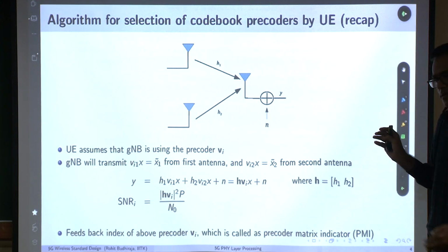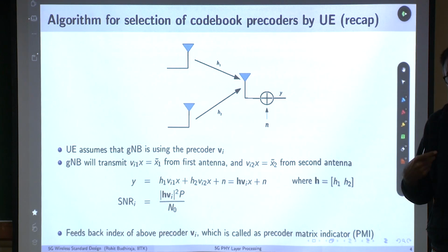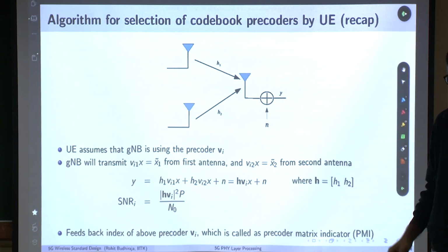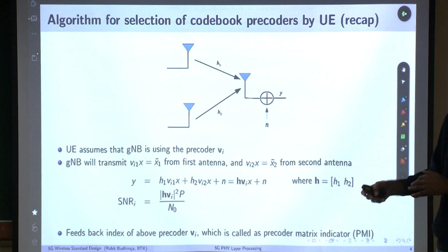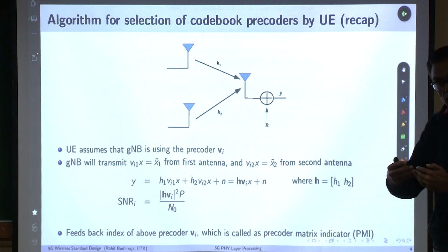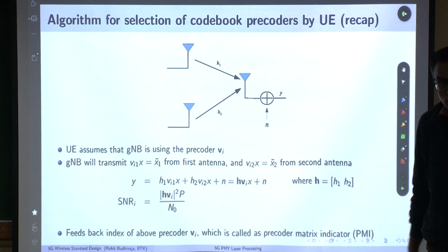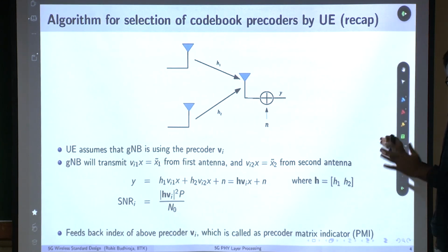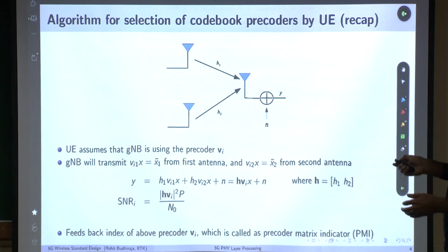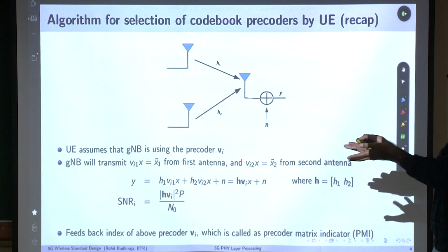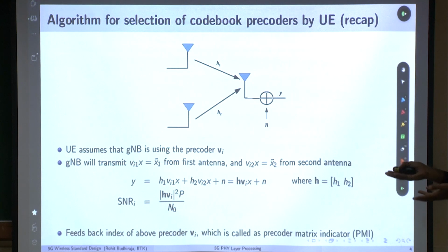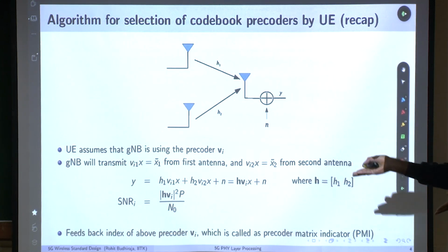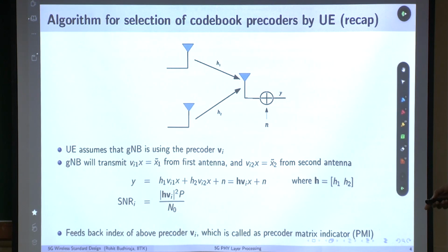And you see this is because the UE has one antenna, and then it implicitly knows that the rank of the channel is 1, right? And if it has 2 antennas, I am going to discuss that it will have to feed back something called rank information also, okay? So along with precoder matrix indication, it feeds back RI, this is called rank information. I will tell you how all that is done. So we will have to extend that system model, right? Because in this case it is a simple model wherein the rank is 1, and the precoder matrix indication is whichever out of those 4 entries, okay, right?